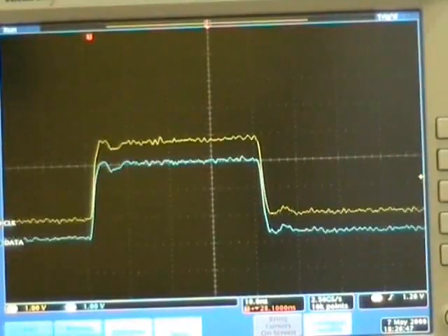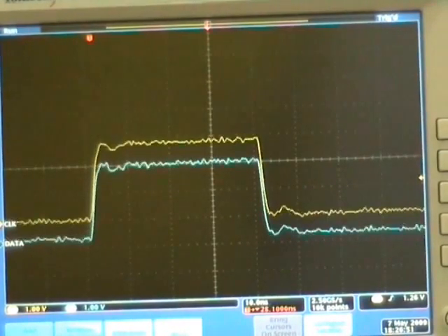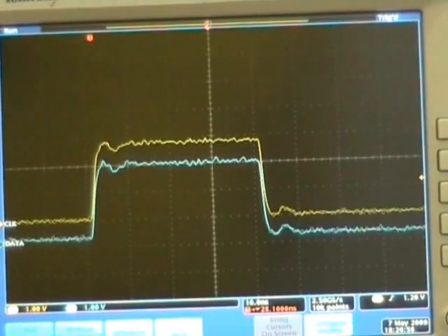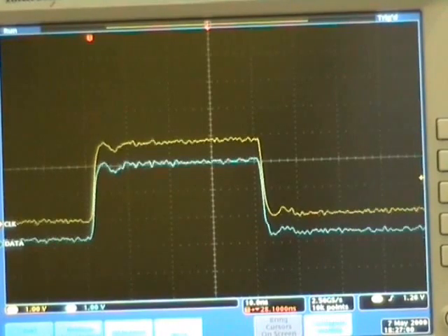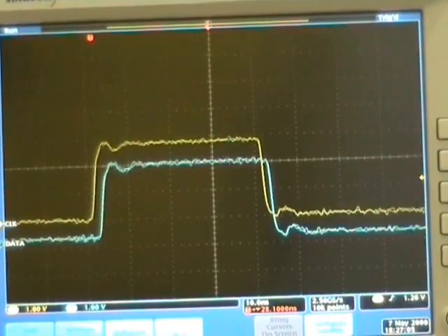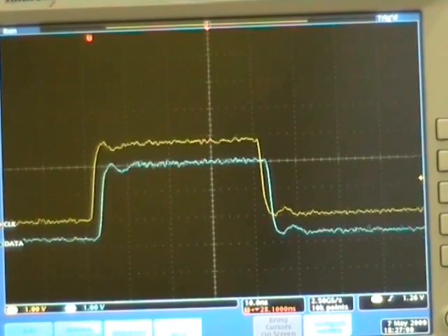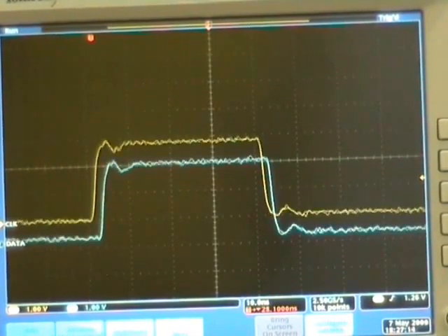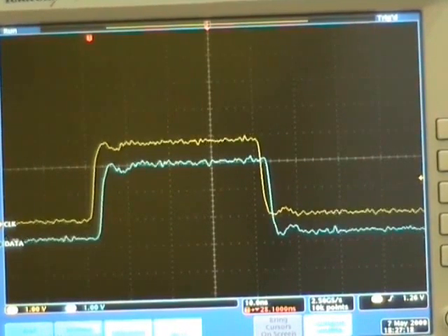Now if we program the rising edge position of channel 3 of the digital I/O module to be 7 nanoseconds, you can see on the oscilloscope screen that the blue curve, which represents channel 3 of the digital I/O module, moves to the right by 2 nanoseconds. This shows the capability of the digital I/O module to program the rising edge position of the digital pattern. In fact, we are able to program 4 edges within a cycle for any digital pattern.